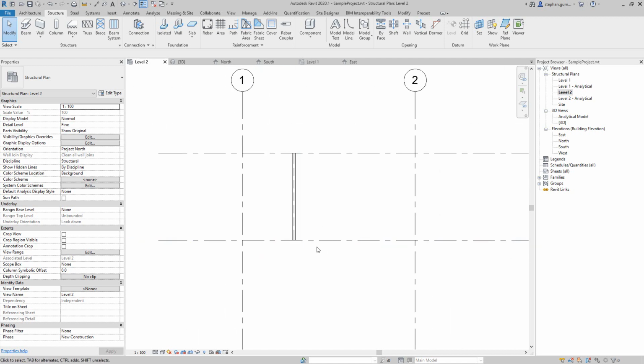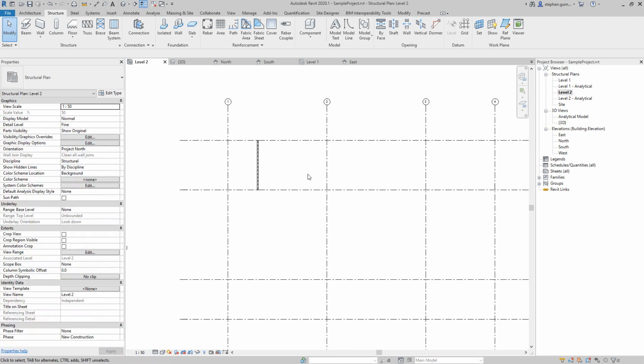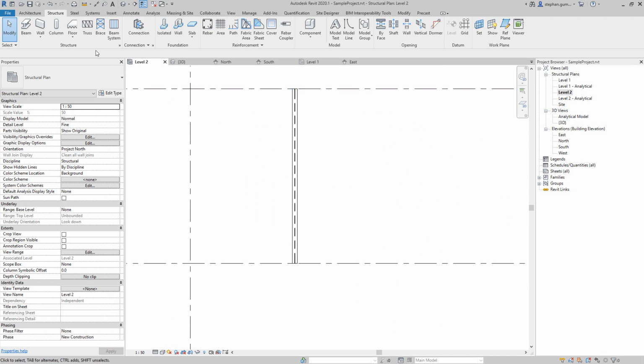This is important because this level of detail affects only this view. So if, for example, you want to take this view and it should be a 1:50 detail, we can change the scale. You can see the representation of all the objects in that view is going to be quite different, and how quickly things change.